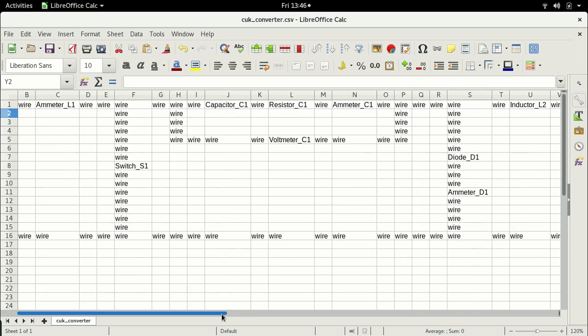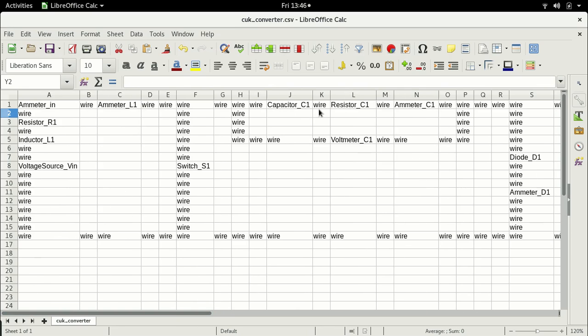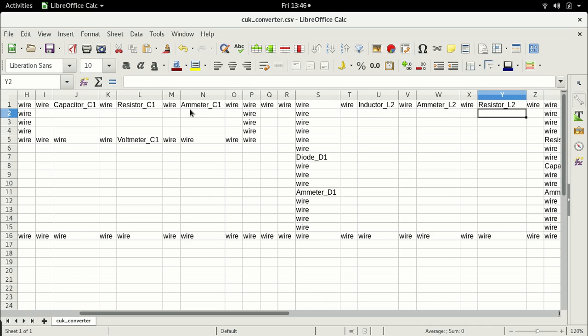But the inductor will now, the capacitor will, or rather the input charges the capacitor through the diode. Now the diode conducts. So therefore the current flows in the clockwise direction again, but through the diode. The inductor, which was first initially being charged by the capacitor, because the capacitor was charging current through the inductor in the anti-clockwise direction, will continue to flow, because remember, the current through the inductor cannot change instantly, and it cannot reverse direction instantly, which means this will continue to freewheel.